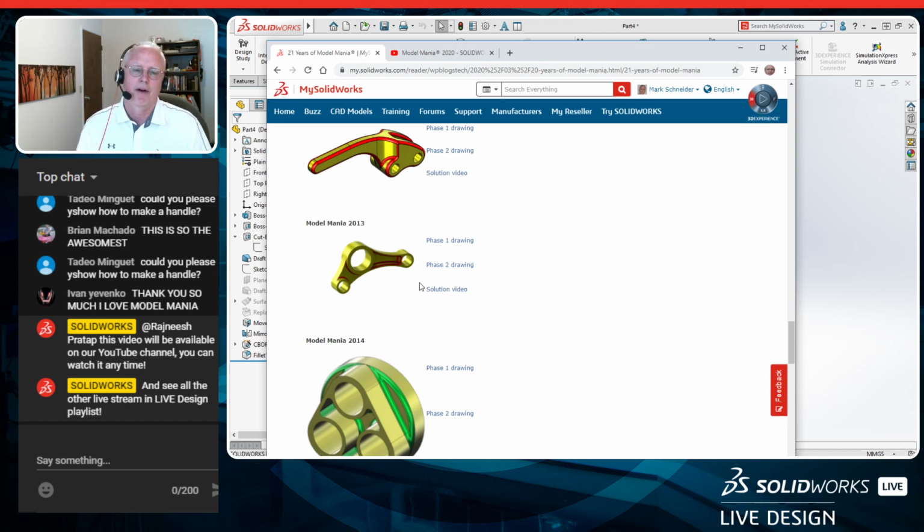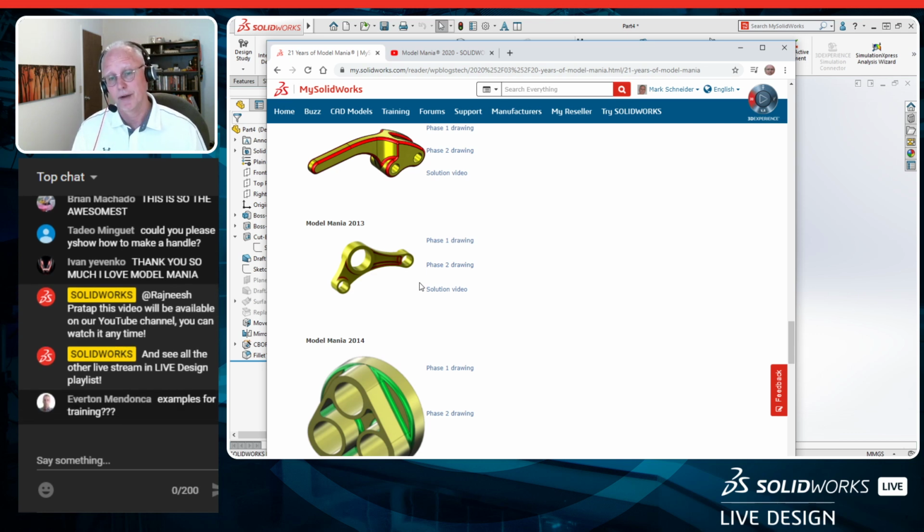And like I said, part of it is just here. There's 3 ways to put that draft on that face. Every one of them is valid. Every one of those solutions is valid. You get to choose which one might work for you, but I think it's important that you understand that these techniques and methodologies are available, so that when you stumble across something that's a challenge down the road, you can do it. Remember, we did that face fillet. There were very few people, when I graded all the parts, that actually used a face fillet to do that.